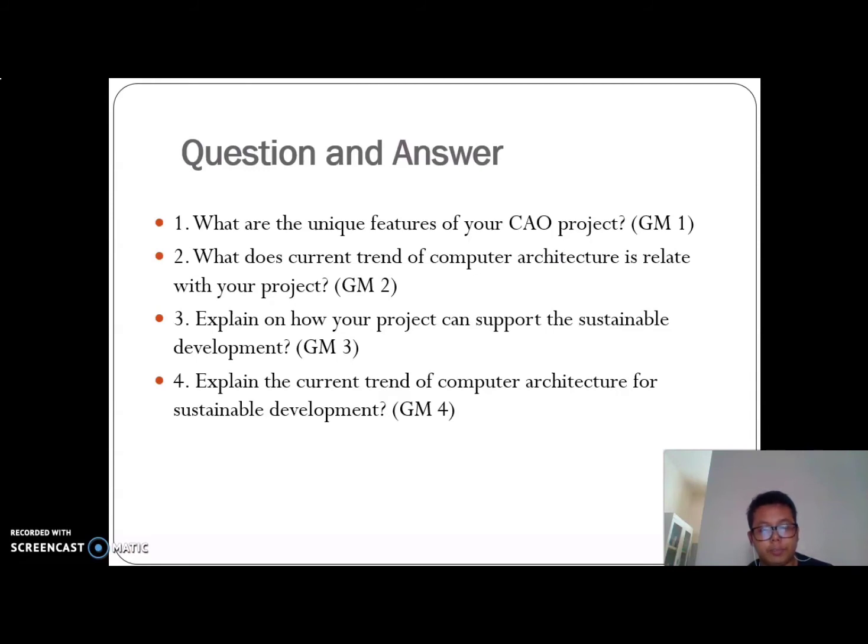applications. So DMA can lead to cache coherence problems. For example, if a CPU is equipped with a cache and an internal memory, then the data the DMA controller has access to, stored in the RAM, may not be updated with the correct data stored in the cache.